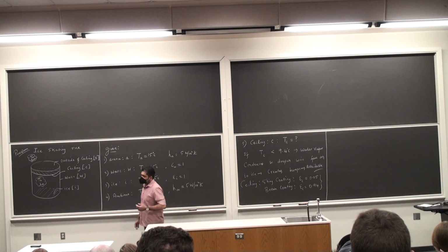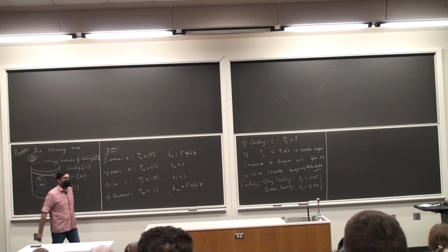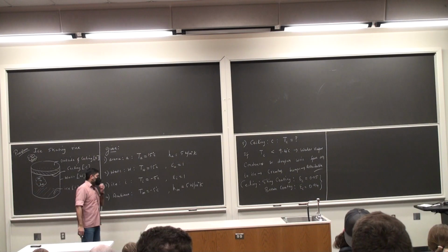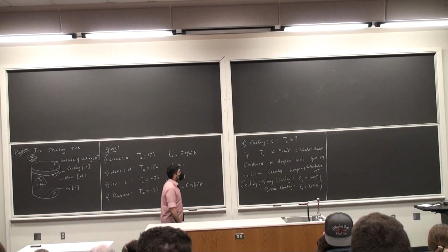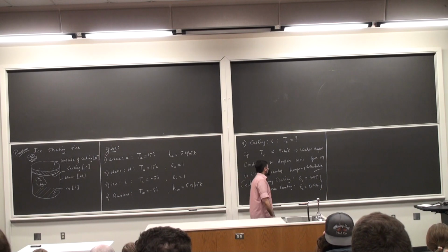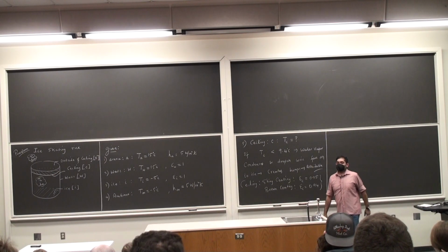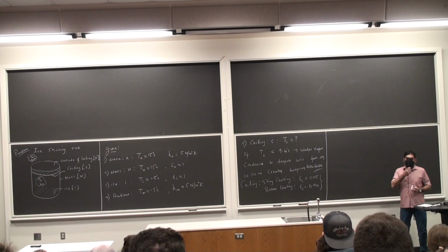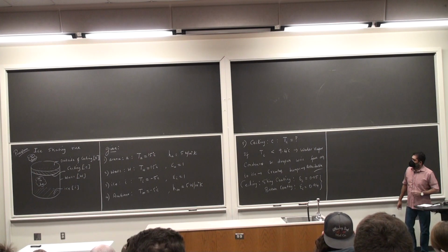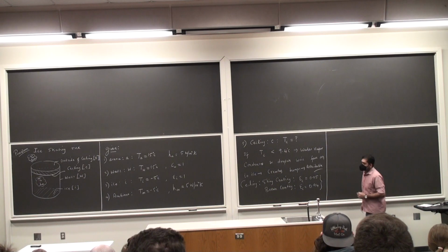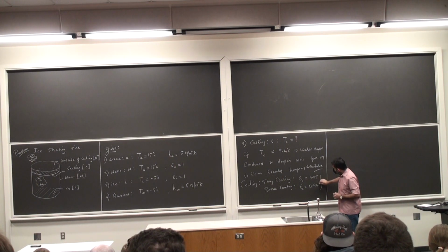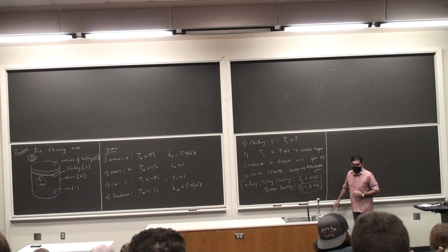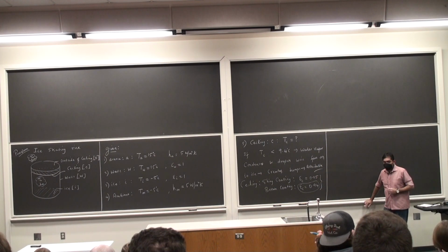Based upon epsilon C being 0.05, there will be a certain temperature of the ceiling, considering the conditions within the arena and outside. Based upon 0.94, there will be a certain temperature for the ceiling. And the idea is, okay, which one should I choose? And this is the whole problem. There is great suspicion that one should not choose this because nobody paints their ceiling brown. But there is also a reason why you should not choose it.